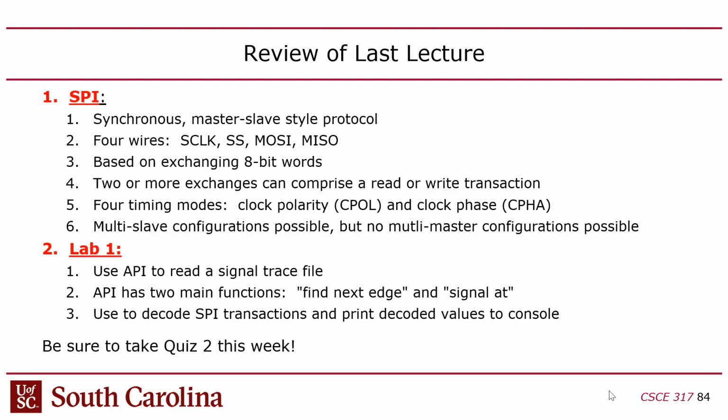You guys with me? So if CPHA is 0, then the first clock edge is where you read the data, where both sides read, because remember they're exchanging, so both ends are reading. And they're both sending data too, but as I explained last time, they send the bit out a half clock cycle before it's read. So if you look at the timing diagram, when you read a bit, you're supposed to have that bit stabilized, meaning that it probably changed 1/2 clock cycle prior to the clock edge it's supposed to be read on.